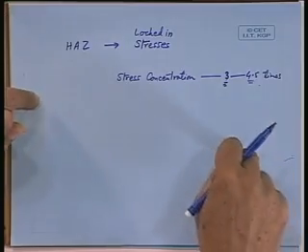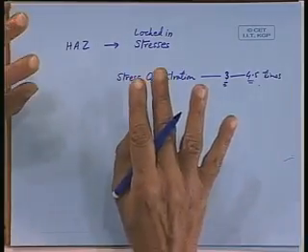And therefore, this cannot be taken very lightly. So, wherever one has any sort of opening, whether it is for the water intake or water exhaust, air intake, air exhaust, or for the hose pipe, anchor chain hose, or chain anchor pocket, everywhere you have some sort of opening, a manhole, a lightening hole, a hatch opening, whatever it is, they have to be strengthened.